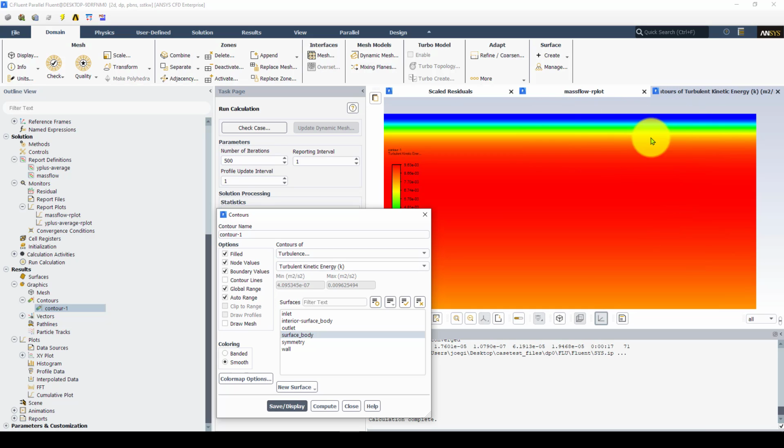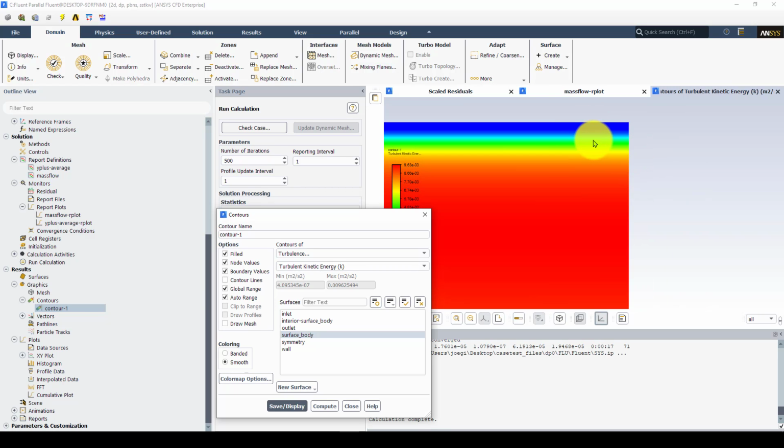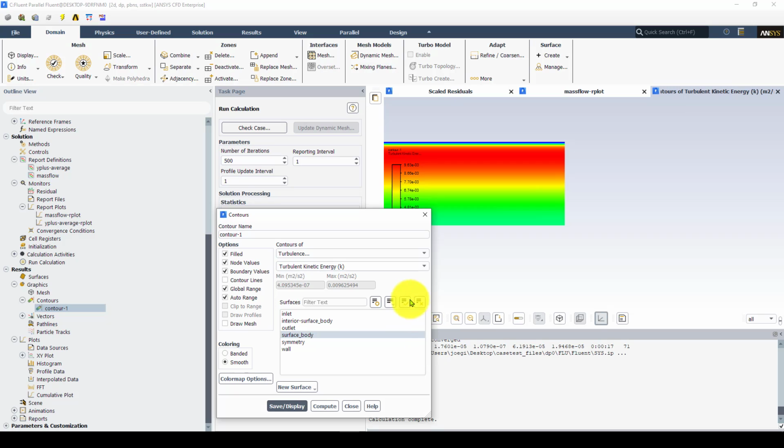We see this in this case that we are resolving the boundary layer. When we are not resolving the boundary layer, now this will be a 0 gradient. It's not 0, the wall will take the first. So we're going to see that when we work the tutorial, but also you can try to redo the mesh and you will see that behavior.